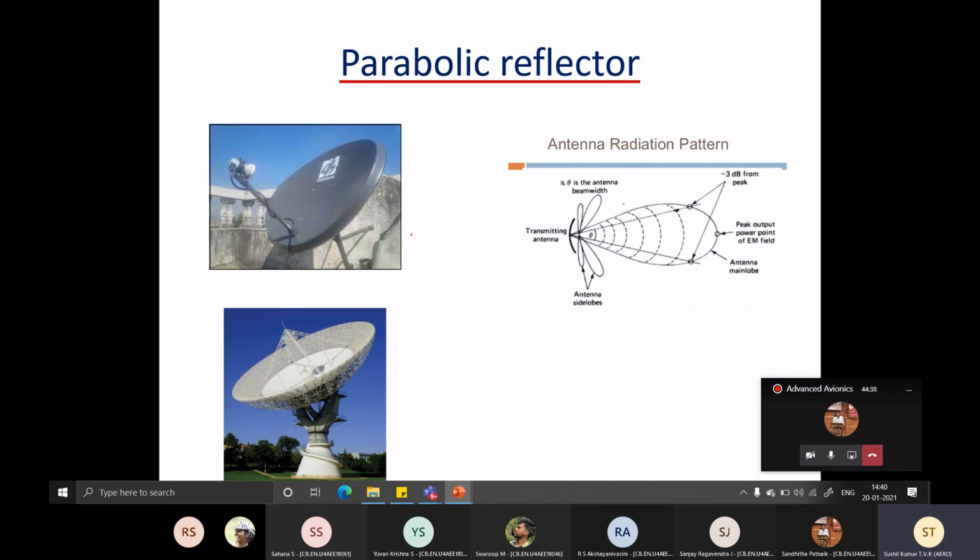They have gone for something called AESA radars. It is Active Electronically Steered Array radars. See, a normal antenna, if you want to rotate it, you'll have to rotate it mechanically. Let's say you're rotating this in the elevation plane. You'll have to move this mechanical stuff. Physically it has to be moved, which means a lot of power and a lot of inertia also.